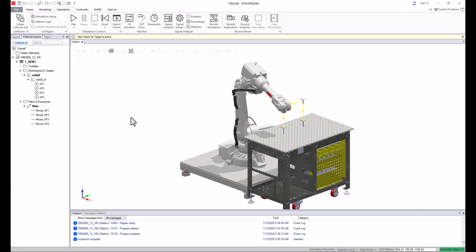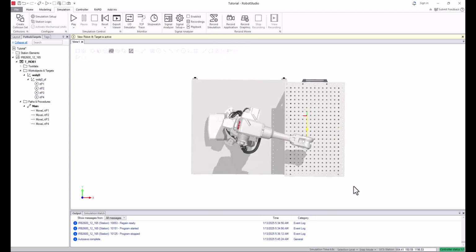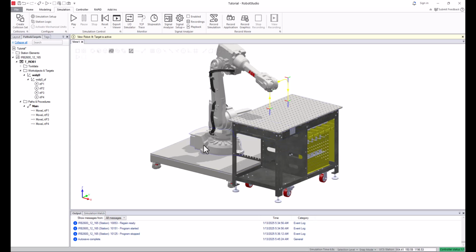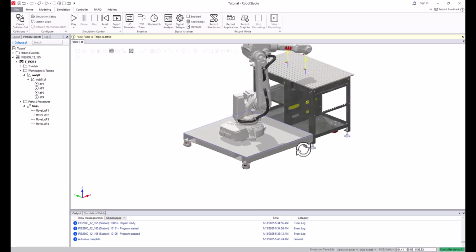So some really important things that I think help you become very efficient is being able to use keyboard shortcuts. Keyboard shortcuts allow us to do a lot of different things. So without moving around in the station here, I can show you that I have keyboard shortcuts for top, left, right, or front, all the different views of the station that I can move the viewer to. That's controlled by the keyboard shortcut, and what I have set up is Control Shift T does the top, D, F, G, H, and B. Those are all personalized keyboard shortcuts that I have.